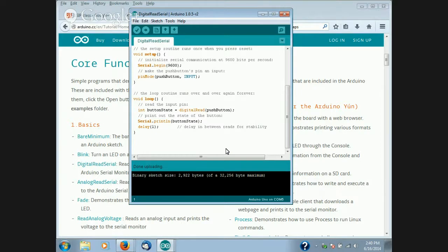With the Arduino Shield, the ADC, the one we got, has a multiplexer built in. So Dr. Leffert said that one should be okay. I said the opposite. Okay, but we still know where to get one. We can find one. That's not a problem. I want either an 8-in, but let's put it this way: Chris's experiment needs 16. Yeah. Okay. So 16-in, 16-bit is what you really need.